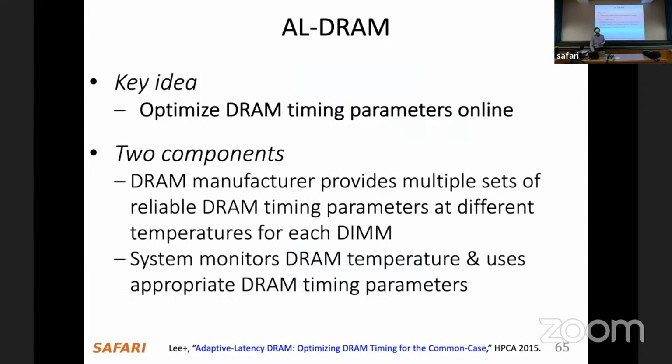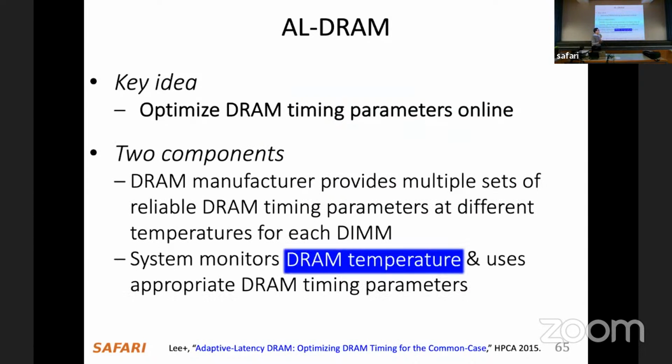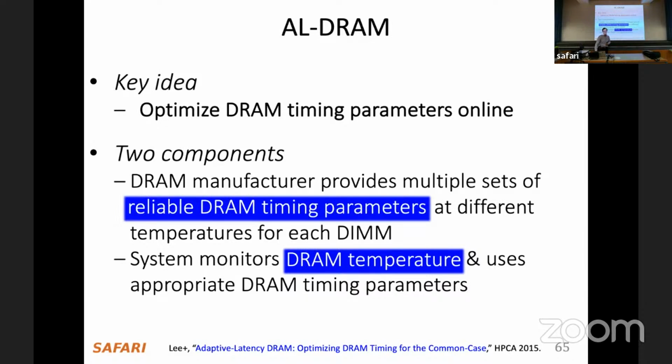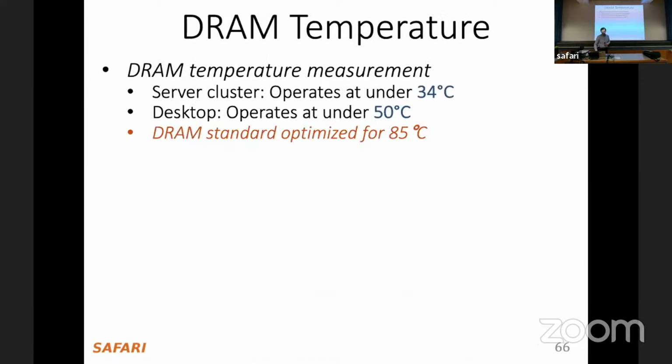So the basic idea, we've gone through this. You monitor the DRAM temperature, and this is actually already done. There are temperature sensors on DRAM chips, and you use the reliable timing parameters for that temperature for a given module or chip. That's the idea.